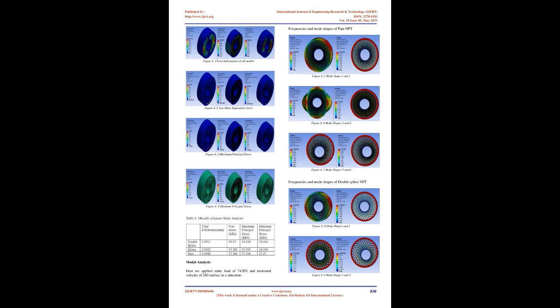Here we need to note that the radius of the pipe shrinks as it reaches the hub of the NPT. It is done to increase the strength of the tire by increasing the number of layers in spokes. The radius of each pipe of the NPT shrinks accordingly with the radius of the whole tire. All 3 spokes are of 150 mm section width. In the above figure 3.1, figure A represents how to design spline structured spokes, figures B and C represent the design procedure for double spline spoke structure, and figure D gives the geometric data required to design the pipe spoke structure.